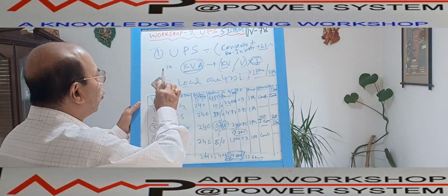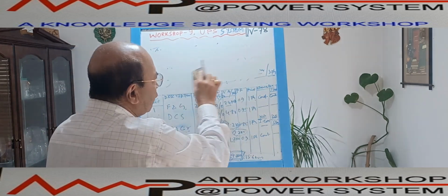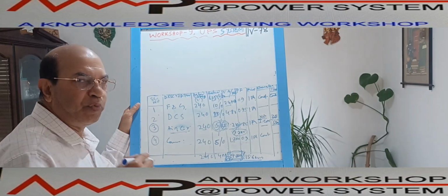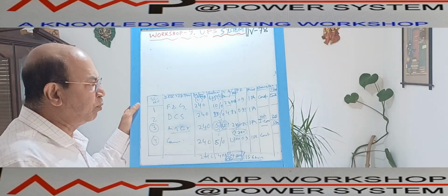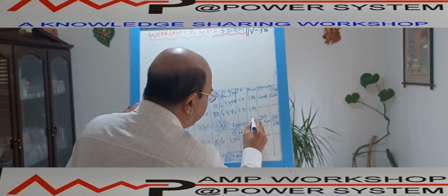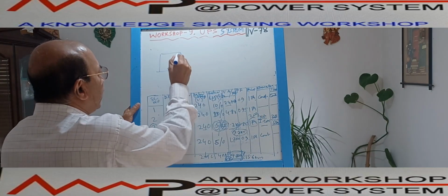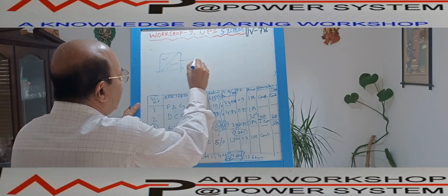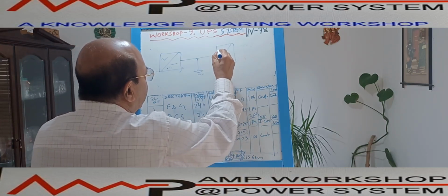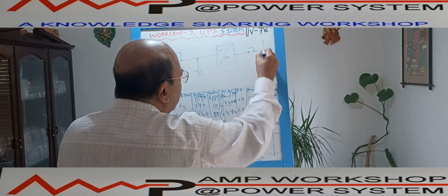Once the load analysis is over, then we have to look into the phases of the load. If the load is all single phase load, that means UPS output is required single phase. But suppose this air circulation fan is a 3-phase fan. We have seen the configuration of the UPS, how it is. It is our rectifier. This is AC supply. This is DC. There is a battery connected over here. And then I have an inverter. Supply is DC, output is AC. This AC is going to the output breaker. It is going to the load, right?